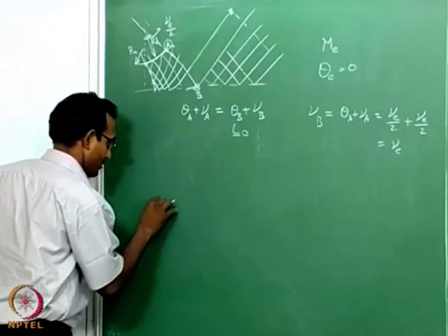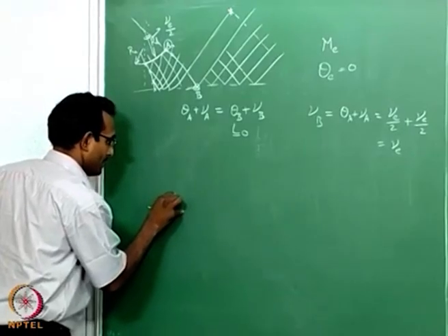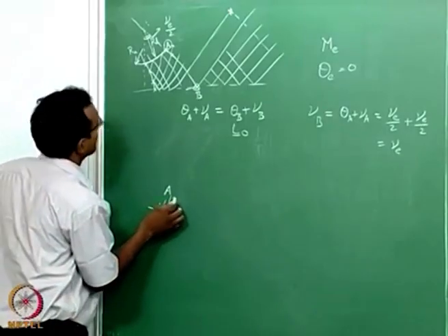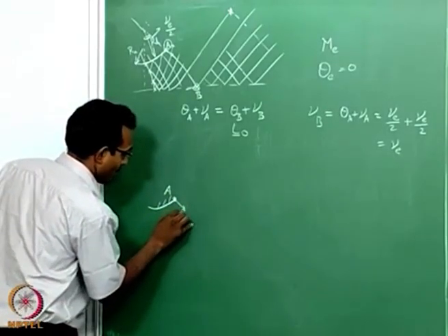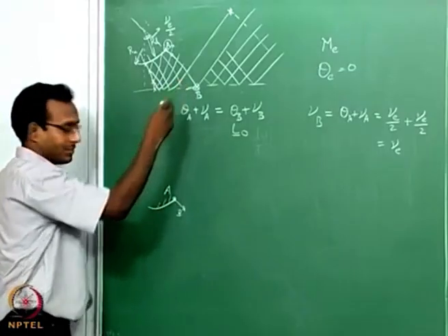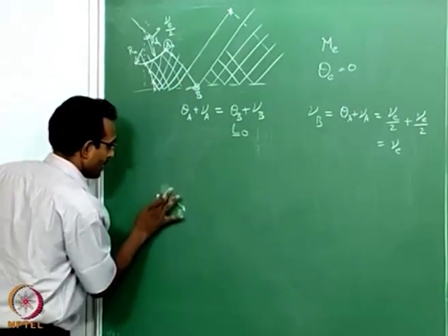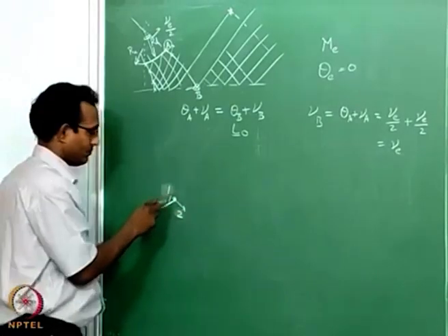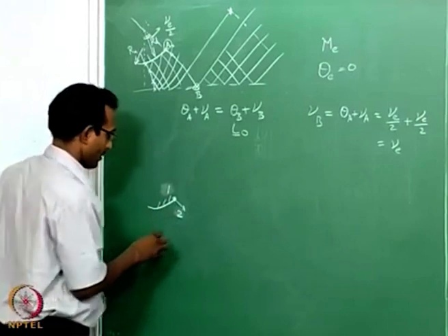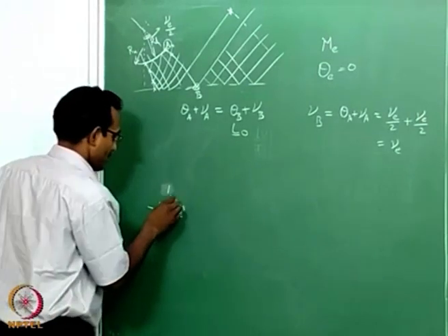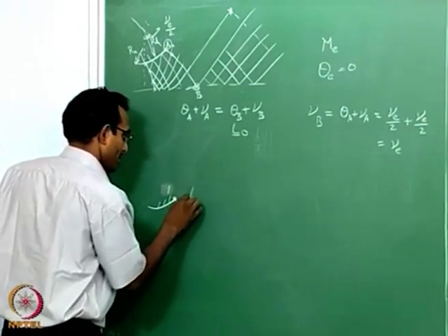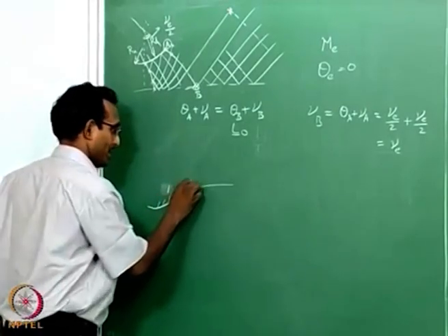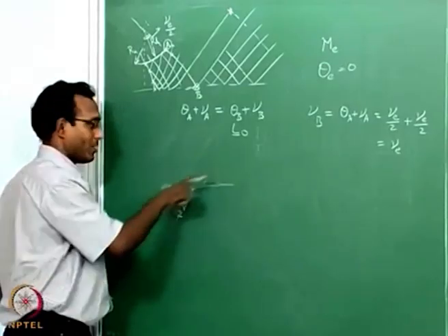The way to think about it, this is my point A, which is already known to me. Now I have a point B. This is different from the other B there. Let us say I will use 1 and 2. Point 1 is already known, point 2 is known now, okay, from some other interior line. I want to create a wall point 3 where my curve will go some other way. This is my new creation, this is my nozzle design.